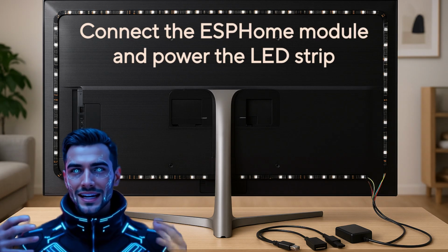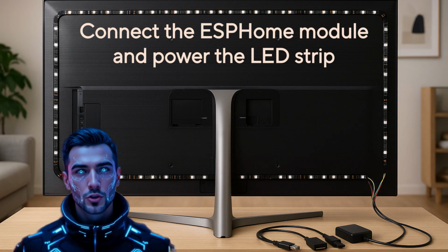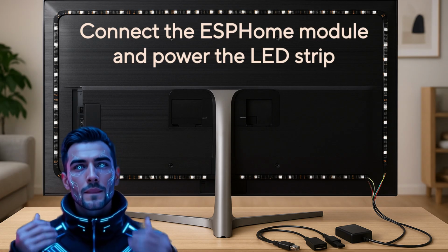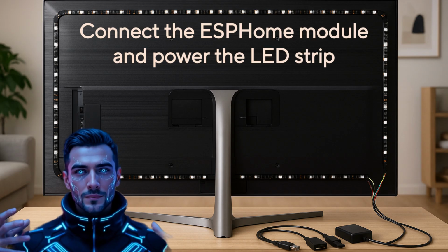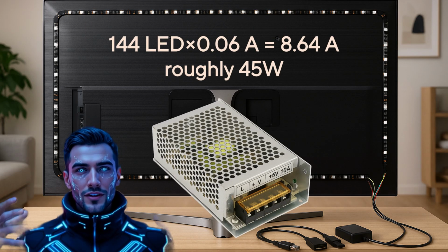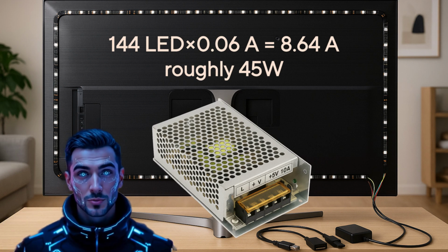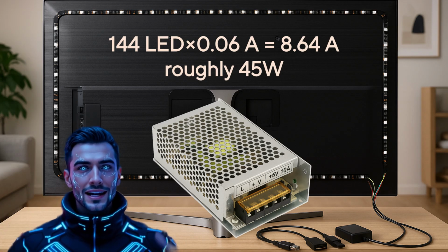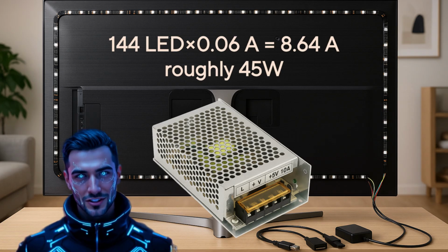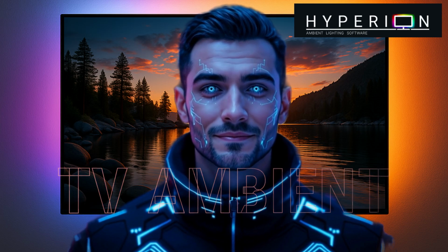Connect the LED strip to the ESPHome module we prepared in the previous video, or to any LED strip controller supported by Hyperion. Then, attach it to the back of the TV using double-sided tape. Use a suitable 5-volt power supply. Each WS2812B LED consumes about 60 milliamps at full white brightness, so 144 LEDs draw around 8.64 amps, roughly 45 watts. And now, let's see how to install Hyperion.